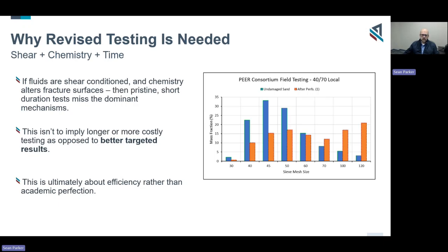And not shown is what was in the cup. I suspect if they had sieved the cup, you'd be more into a 100-200 mesh proppant. So there's a considerable difference between thinking I'm putting 40/70 into my formation when in fact you're effectively putting in dust.